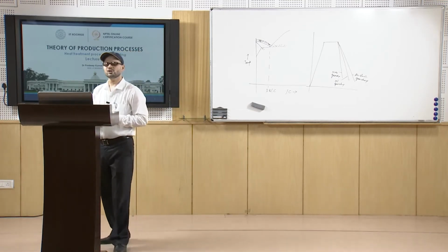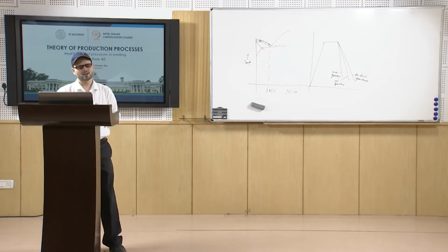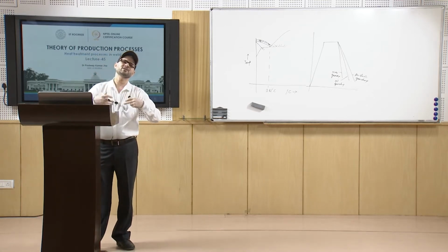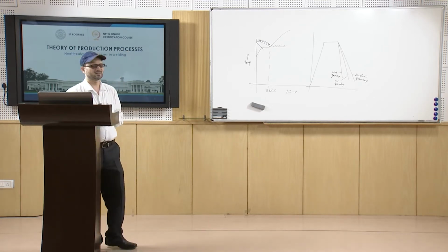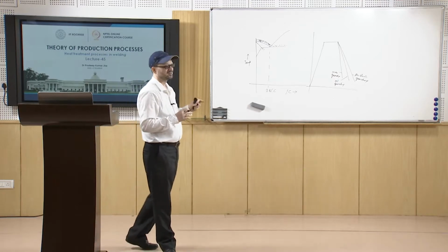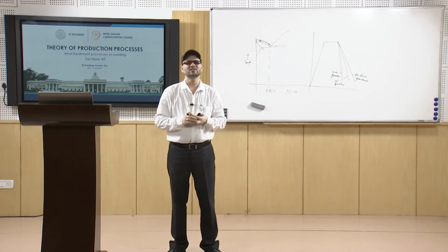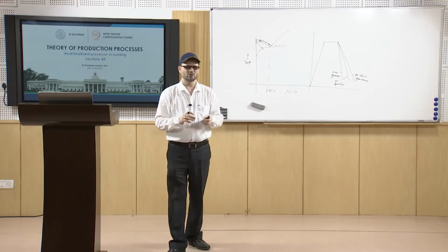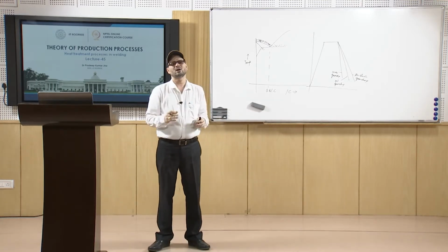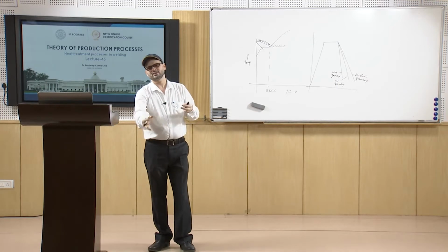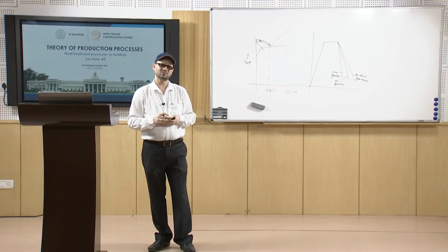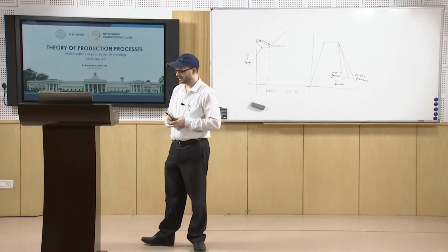So, to reduce this hardness, a tempering treatment is required, so that the brittleness of the phase achieved because of the quench hardening is reduced. Many a times when we do welding, we put it in the water quickly, and that leads to that type of phase.